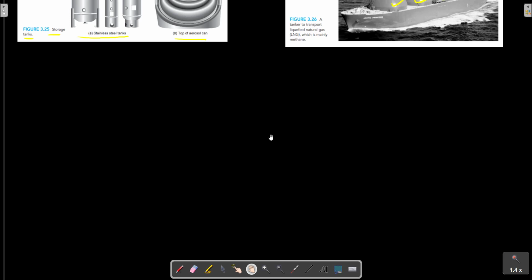When the refrigerant condenses, the temperature is determined by the saturation temperature for that pressure, so the system must be designed to hold the temperature and pressure within a desirable range. This figure shows the compressor and the condenser of the refrigerator as an application of thermodynamics.